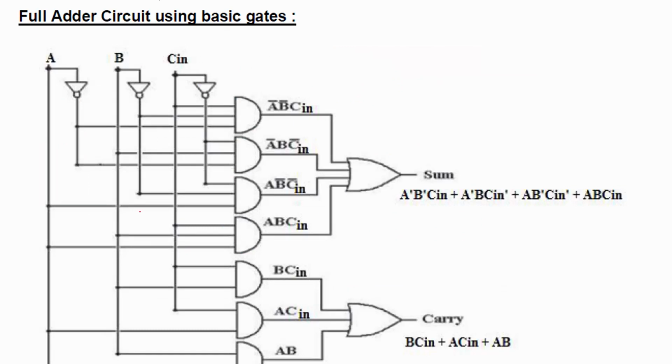Just like our previous half adder circuit, after drawing this diagram neatly, we need to mark the gate IC numbers properly, decide which input is given to which pin of your different ICs, and which output port will generate which intermediate result. Mark all these input output ports properly in this diagram, then it will be easy for you to connect any such complex logic circuit. It will generate the exact result without any mistake.